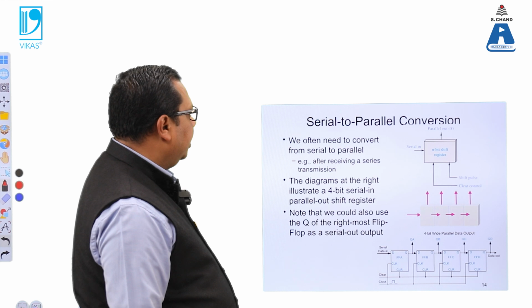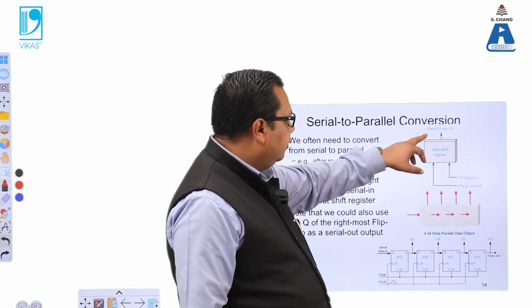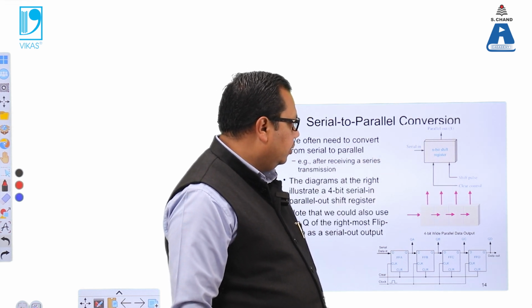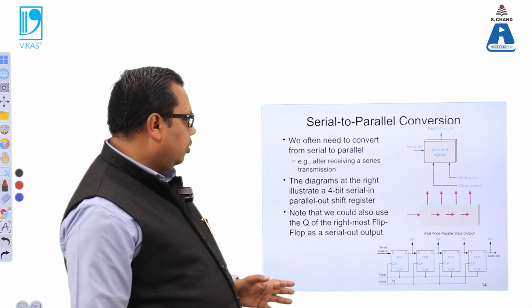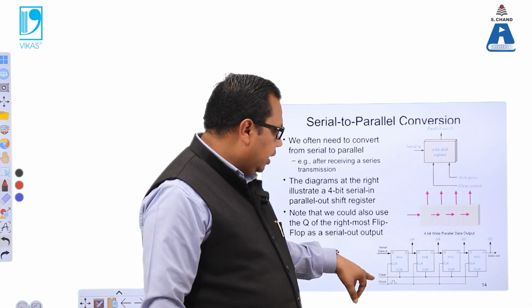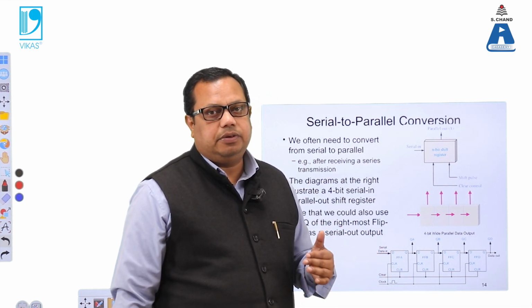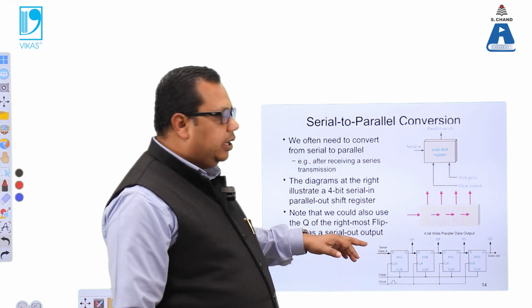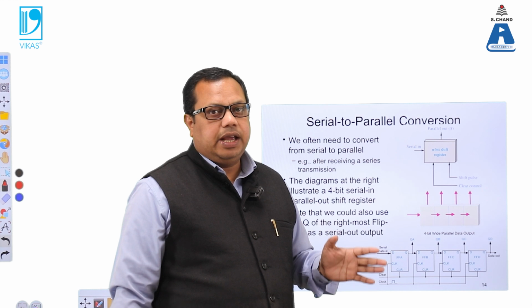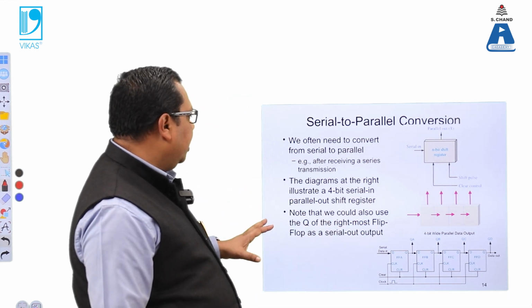Then we have serial to parallel conversion. We can see that this is an n bit register, which has a parallel output, there is serial in, and then a shift pulse and then clear control. So we have a parallel control here where we can make the data serial, then there is a clear and the clock. Again, with different varieties of input and output, we are letting the data break into small bits and the time be broken into small time pulses. So this is basically serial to parallel conversion.